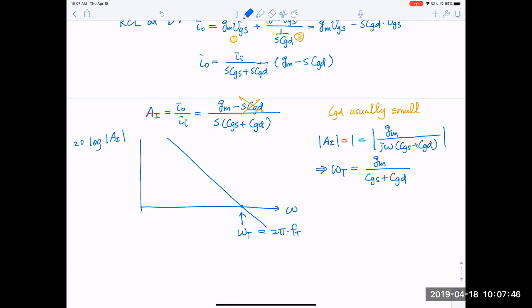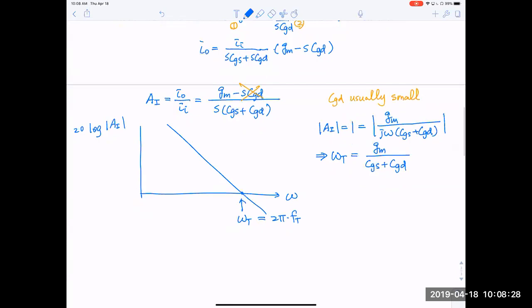It's next to impossible to design a circuit that has a functional gain beyond the fT. Usually that's not possible. So this is the upper limit. If you become a circuit designer and you pick, say, a TSMC 10 nanometer node, and fT is 300 gigahertz, you kind of know what type of circuit you can design into this. If people say they're going to design a terahertz signal, well, they need some magic to make it work using that technology node. Okay, so that's fT.